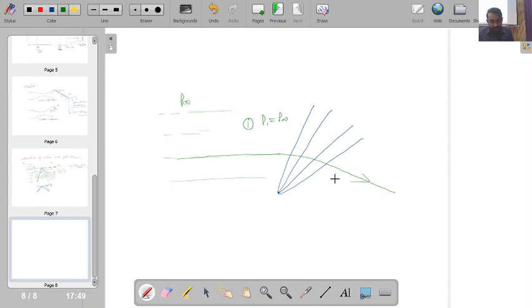Okay, and in the far stream also, say this is my streamline at the far stream. Above this entire streamline I have pressure P infinity. But when the flow has gone through the number of expansion waves, this pressure P2 will be less than P infinity.